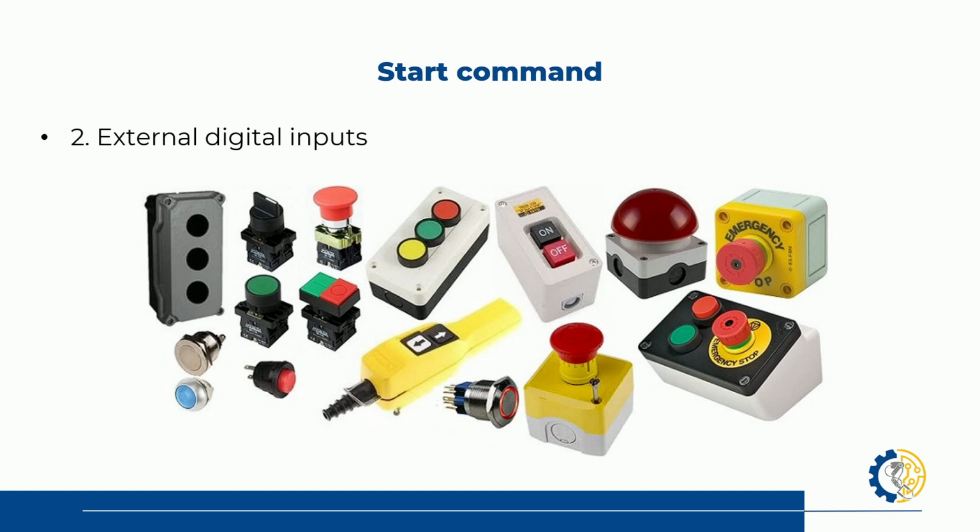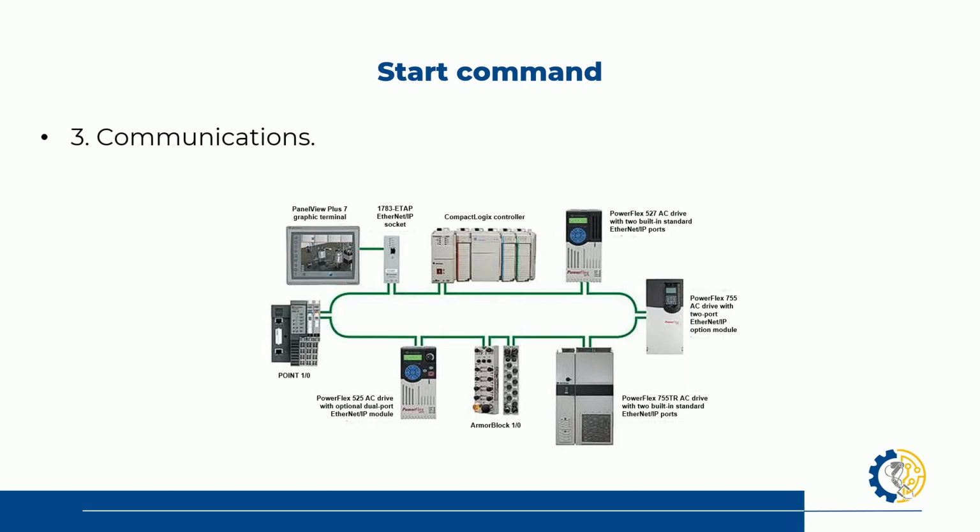So we need to connect that emergency stop with a digital connection, and that digital connection needs to have a parameter specifically for the emergency stop. But we're going to check into this further down, with the communication part. So this is what I was telling you: I don't have any cable at all for stop or run or reverse or jog, nothing at all. I have everything here connected with one only cable.